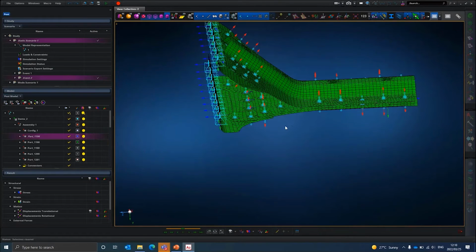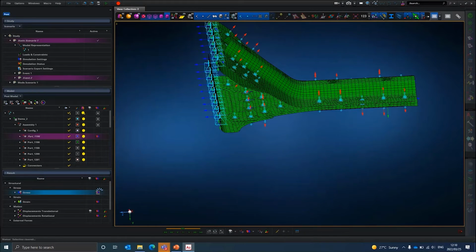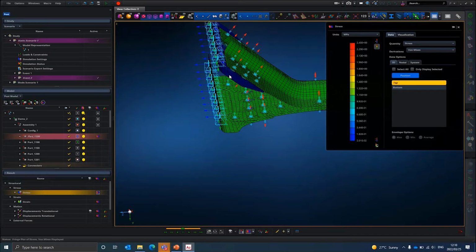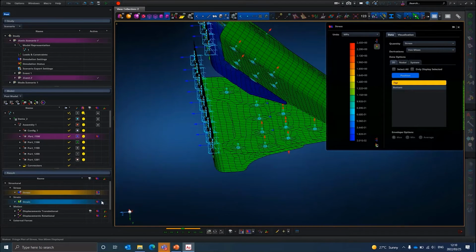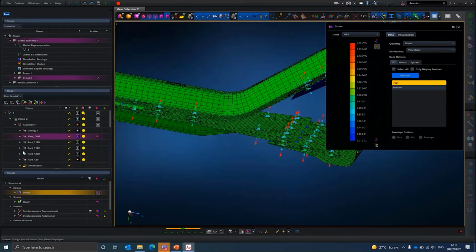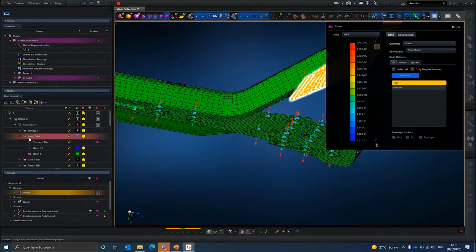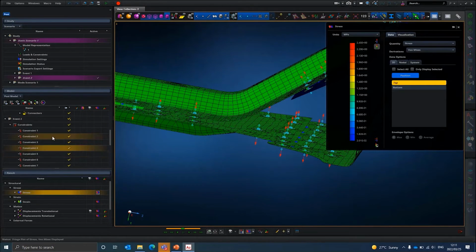Now, what you should also just remember is there are no results there. When you select a new part, you just need to toggle on and off the fringe plot that you wanted to plot. So you can see now I have results only for that specific part. And you can do it for any part that is in this specific model that you've analyzed. But you also have the option of, for instance, selecting something like a constraint if you want to see reaction forces.